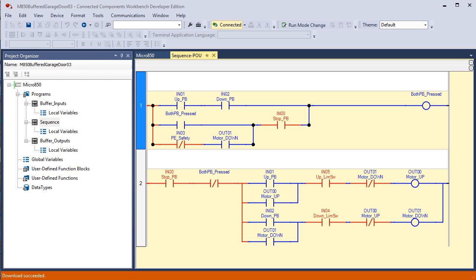I would like to add something about that PE safety. Photo eyes originally came with mechanical contacts in them, a normally open, normally closed Form C contact, and some of them had timers built in for time delays, and they also had a switch for light dark operate. And when you flip the switch between light and dark operate, you get the opposite state change in the contacts based on when the photo eye sees light or when it doesn't see light, dark operation. We're not going to get into that.